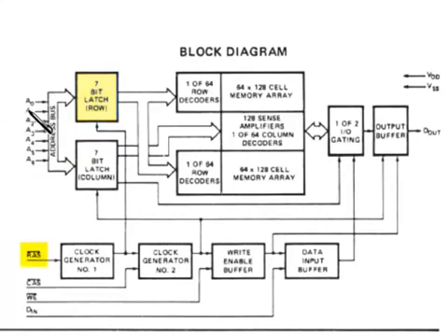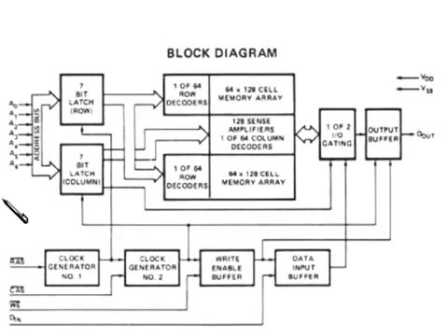Then we're going to change this to columns, and we're going to pulse the CAS, the column address strobe. So actually what we have is A0 through A6 duplicated for a total of 14 address lines. As we know, 2 to the 14th power is the same as 2 to the 10th times 2 to the 6th, which is 16K.